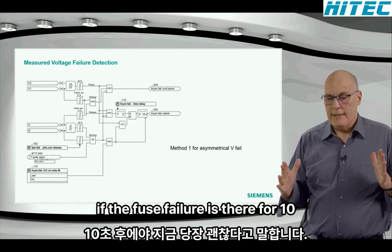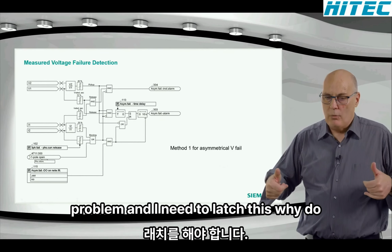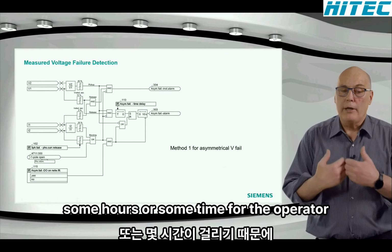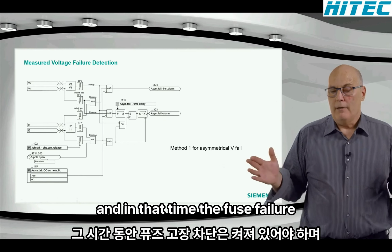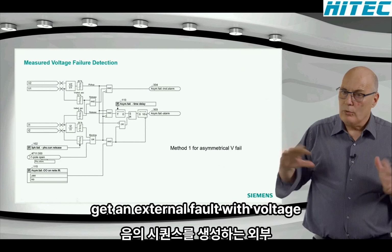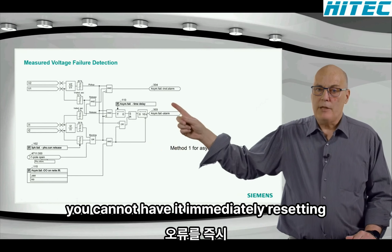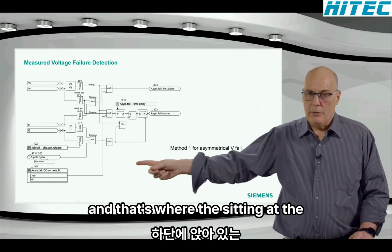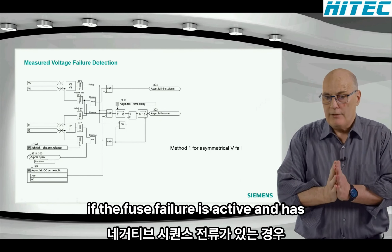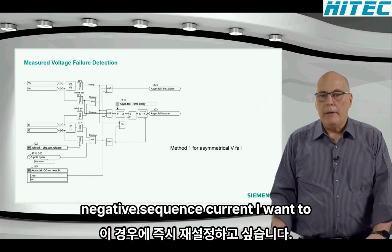If the fuse failure is there for 10 seconds, you say, okay, right now, this is probably some problem in the secondary wiring, and I need to latch this. Why do I need to latch it? Because it will take some hours or some time for the operator to get there to fix the problem. And in that time, the fuse failure blocking must remain on. And if you now get an external fault or some fault in the system, creating negative sequence current, you cannot have it immediately resetting the fuse failure. And that's where the setting at the bottom comes in. Some users want to do this. They say, even if the fuse failure is active and has been active for 3 hours, if there's a negative sequence current, I want to immediately reset.